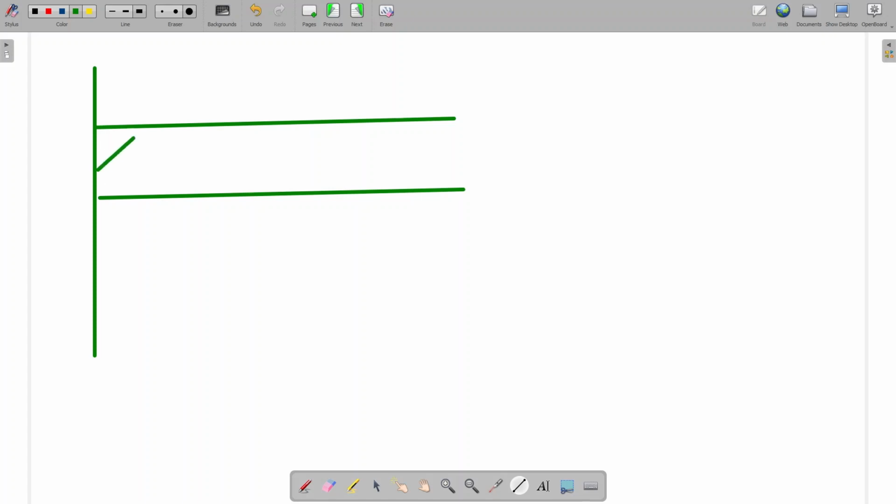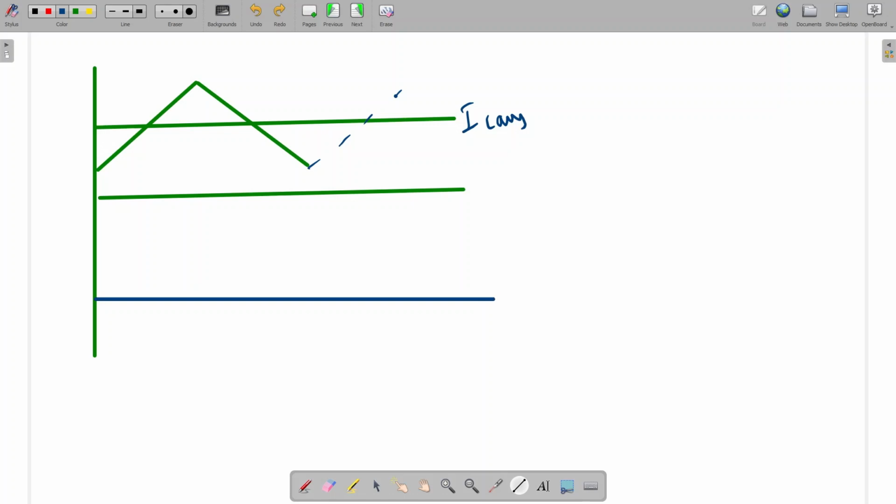So this is the inductor current. This is T on and this is T off. This is IL average. This will follow this path. And the IC current will be here. So IC is equal to IL minus I naught. This is IL and this is I naught. I'm going to draw the IC. So here it will be this.